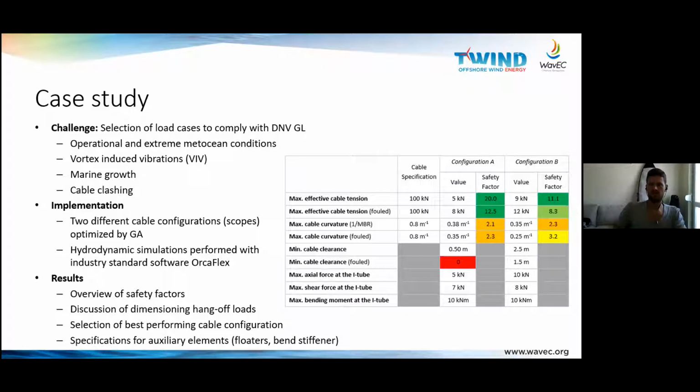So basically, we compared 2 different cable configurations that were optimized and then ran the full cases, like the ultimate limit state and fatigue limit state, with marine growth, checking that the cable is not clashing with the mooring lines, and all those things we can do now thanks to the tool and the optimization process.